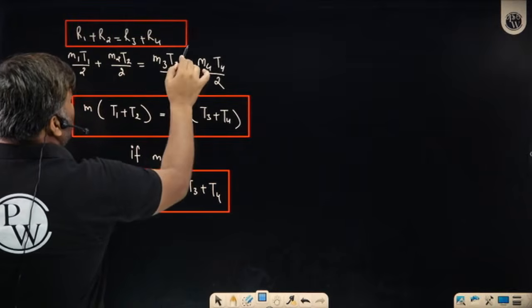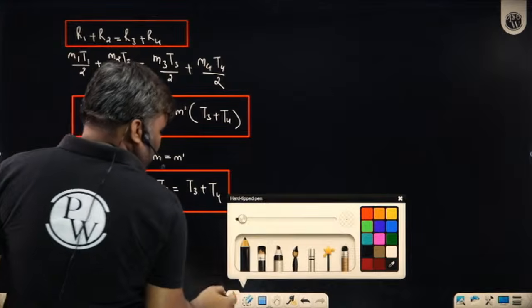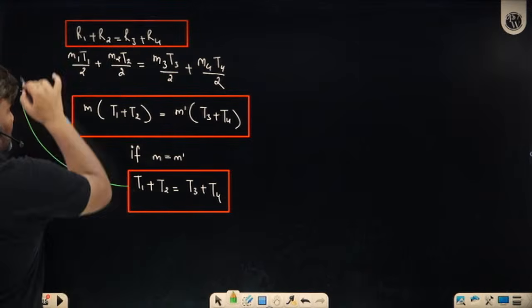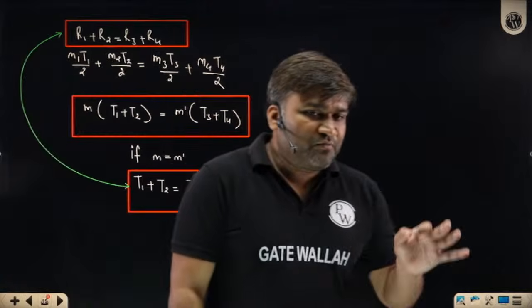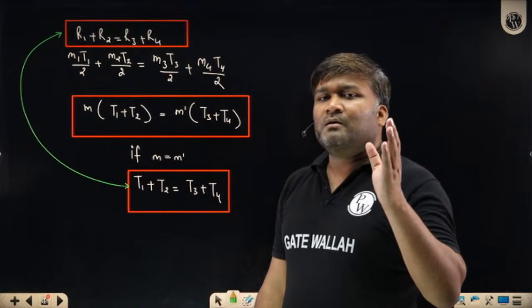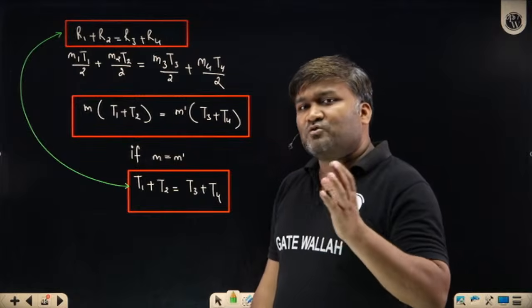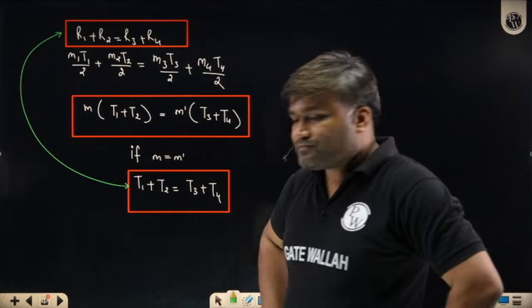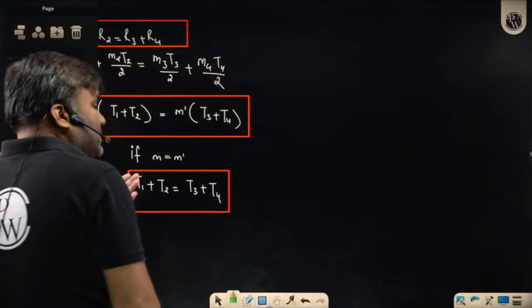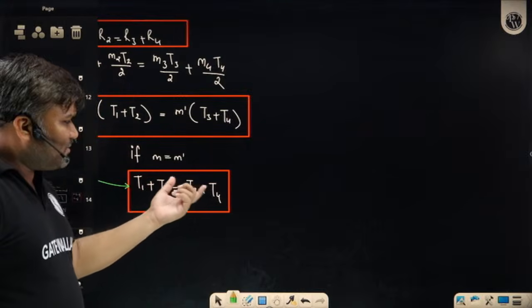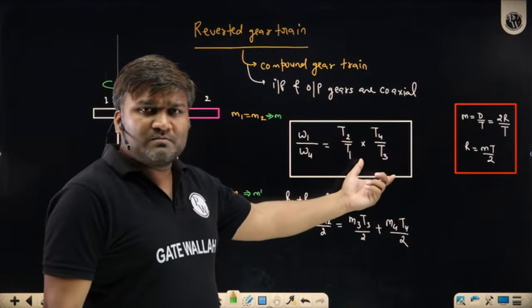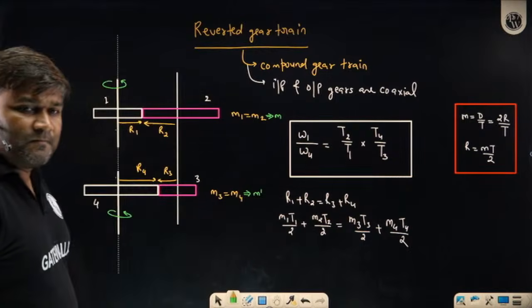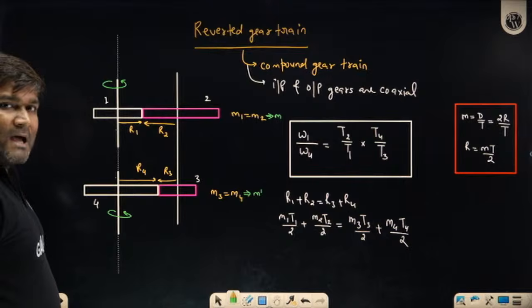And how many of you can feel that whatever relation you have got in the teeth is the same as radius relation. So with the help of this radius logic, if some teeth they have missed, you can find out this value. You can calculate missing number of teeth, and once you have all the teeth with you, omega 1 by omega 4 is not a big deal. Tell me, I hope this is clear.